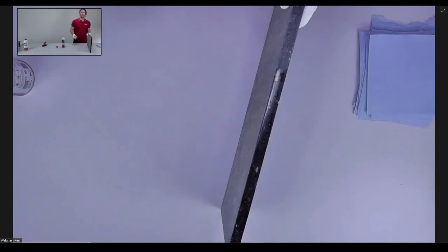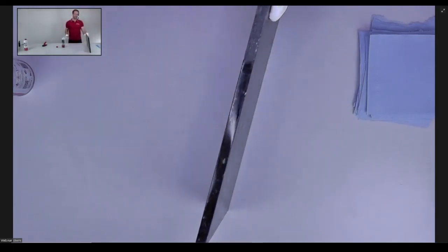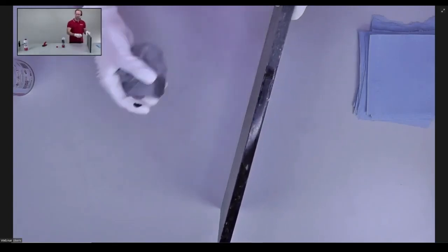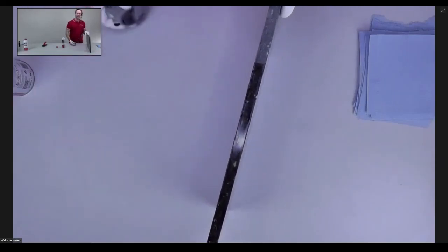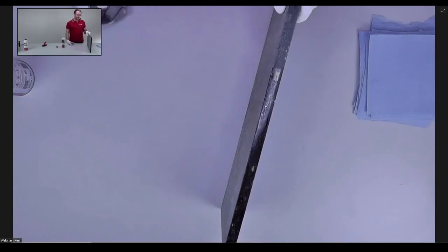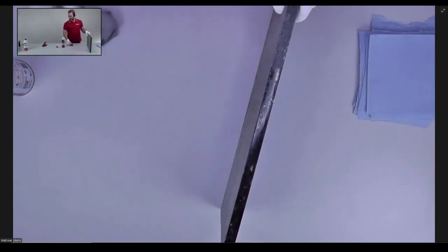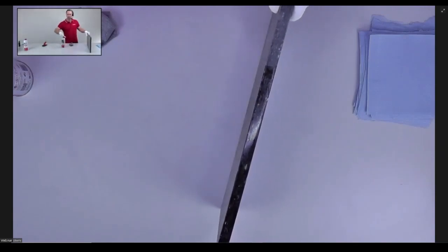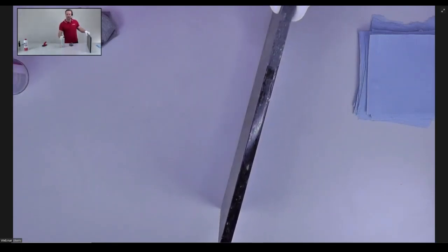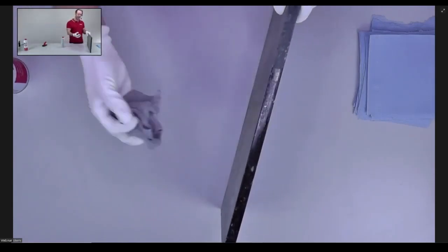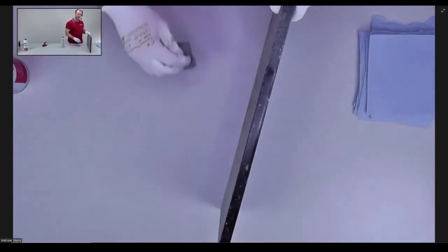And now this, I don't have to leave for 15, 20 minutes on. I just leave it for 3, 4, 5 minutes. Then I remove the excess and I move the piece to the next workstation. Of course, the protective effect, the water, dirt, and oil protective effect also will be developed only after 24 hours. But you don't have to wait a long time for the penetration. So 3, 4 minutes, you wait, and then you just take again a cotton cloth, you remove the excess a little bit, and then you're good to go. But then you have this nice effect.